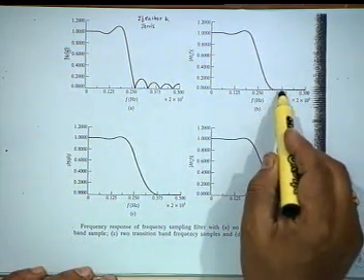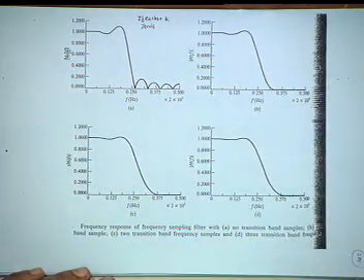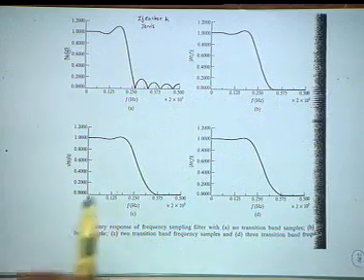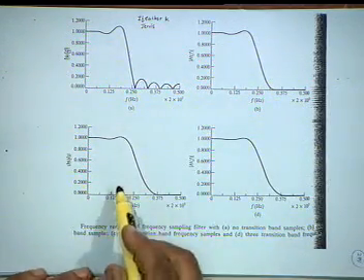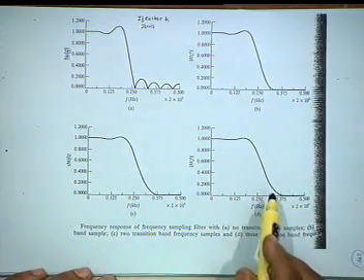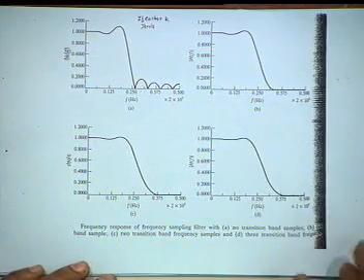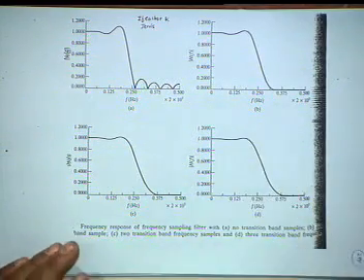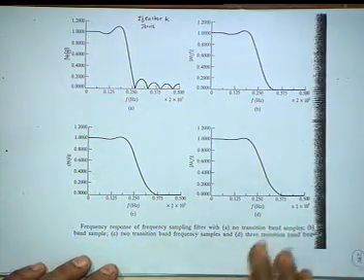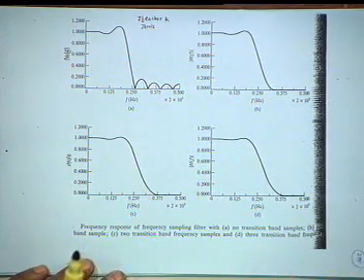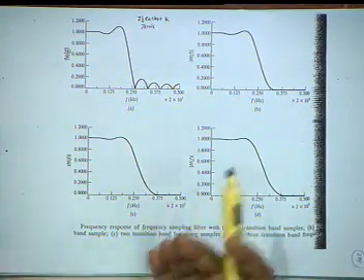Here it goes much beyond, that is its widening, and this effect will be experienced whenever there is a Gibbs phenomenon. This contains 2 samples and this contains 3 samples. If you use more, well, you are widening your pass band, but you are achieving a better pass band response, okay. So, it is a matter of compromise, what you want to give up and what you want to achieve.